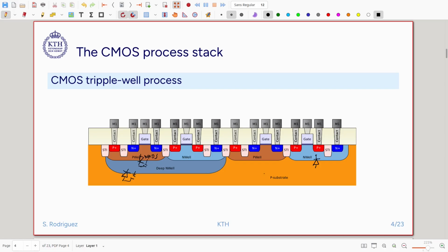here. So the big improvement is actually for the NMOS devices that are no longer sitting directly over the P substrate, because then there is no isolation. So this is the triple well process. Normally it is an optional module that can be added to the fabrication layers.